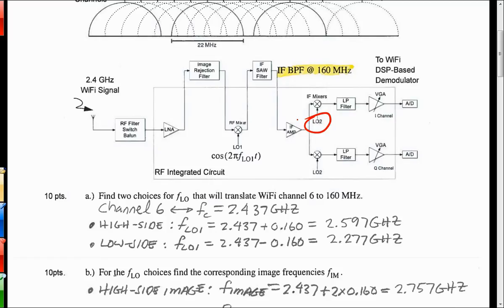It would probably take it down to within a few kilohertz or tens of kilohertz, right down to baseband. And baseband means taking the spectrum and centering it right around 0 or close to 0. There's offsets and other things that show up at DC, so sometimes they take the signal down very close to baseband, but not quite on it. And that's what the second local oscillator would do.